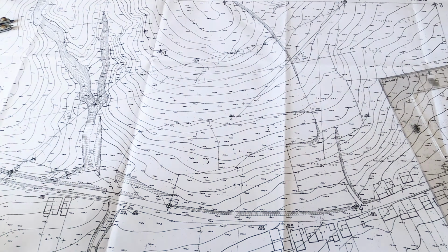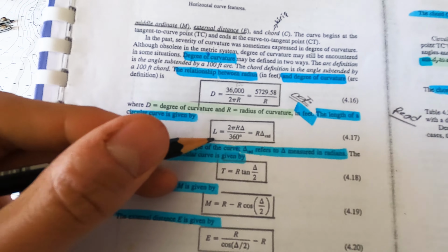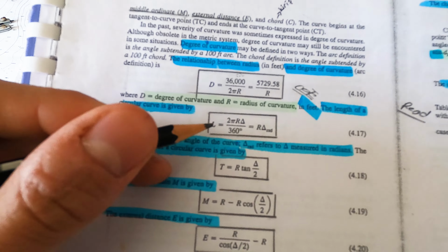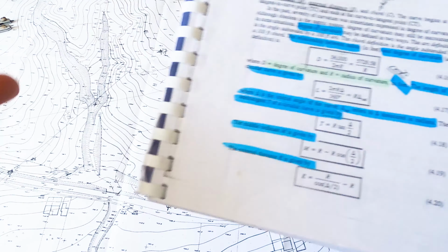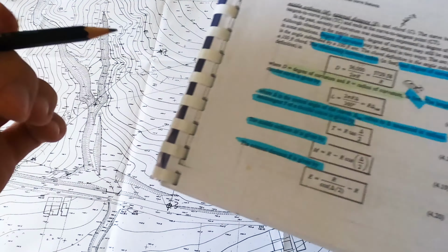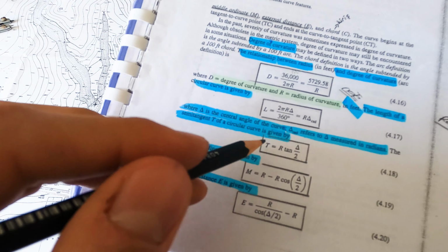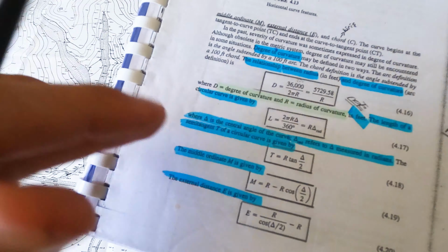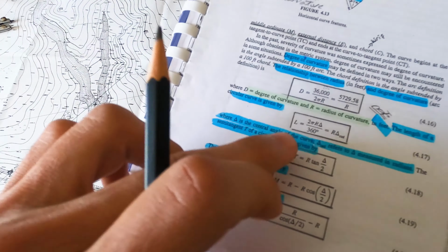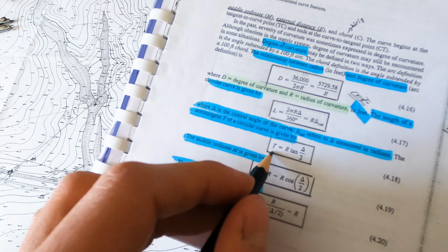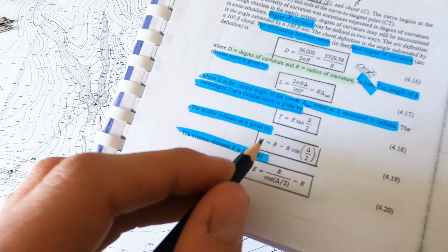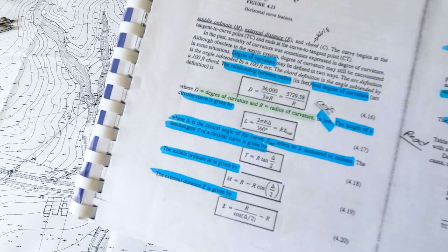What we have to do then? First, we start with the computation of L and T. What's L? The length of the circular curve. And T is the semitangent of circular curve. So we start with T at first, then we go to compute L, and then EC in here.